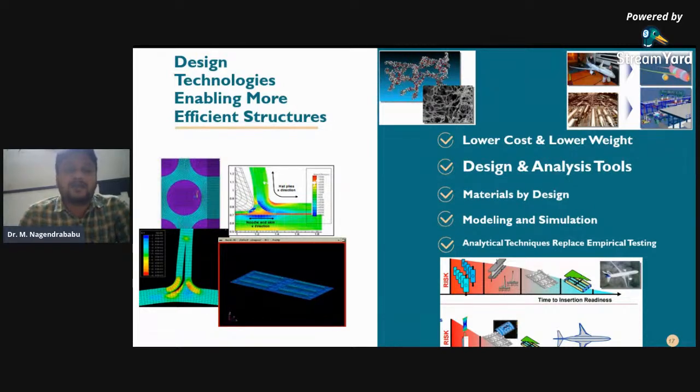Similarly to nickel alloys in its heat resisting properties, titanium aluminum alloys retain strength and corrosion resistance in temperatures up to 600 degrees centigrade, but these are more easily machined, exhibiting similar machinability characteristics to alpha-beta titanium, such as Ti6Al4V, I believe. Perhaps more importantly, these alloys have the potential to improve the thrust to weight ratio in aircraft engines because it's only half the weight of nickel alloys.